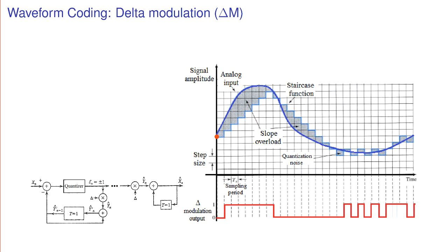My previous level here is this one, and my waveform is bigger than that, so I get 1. Then I go to the next level. Because your input is bigger than the output, so this is the input, and this staircase function is the output.